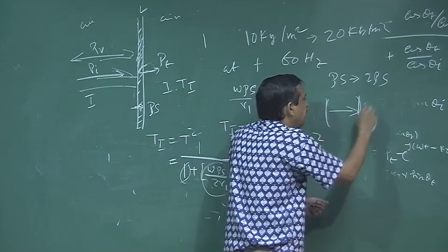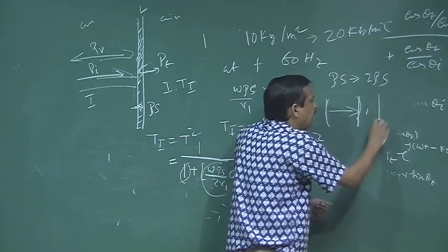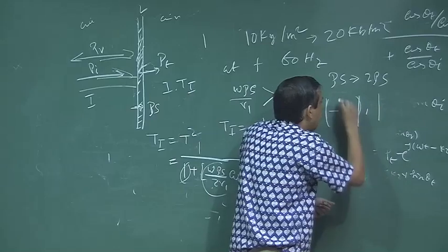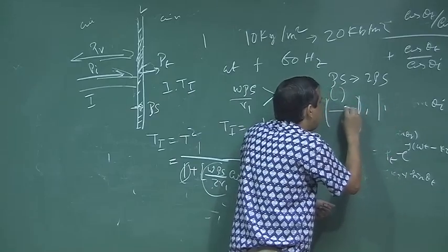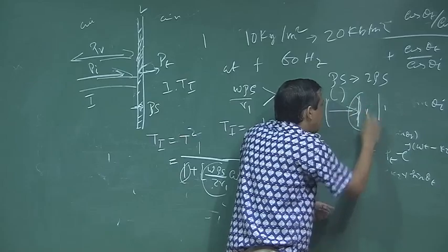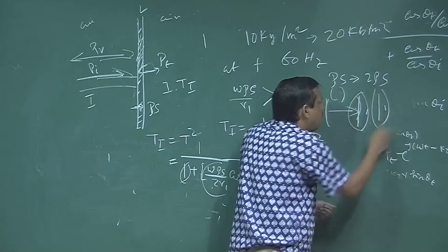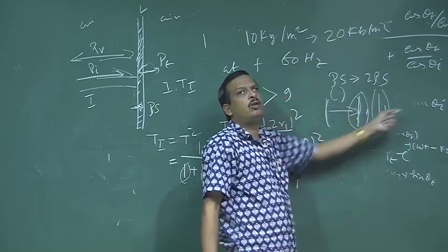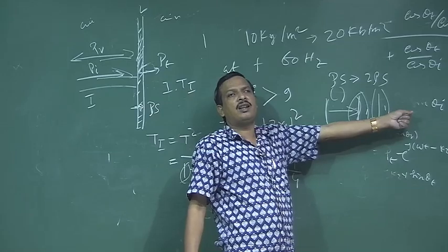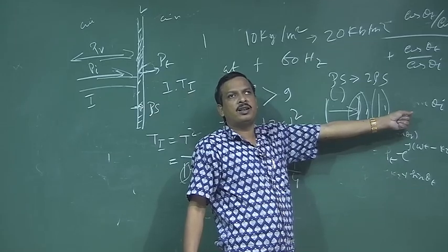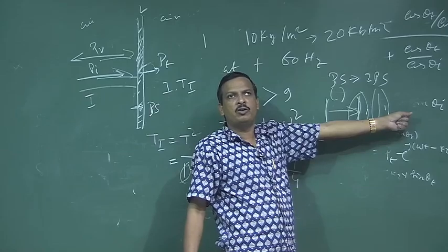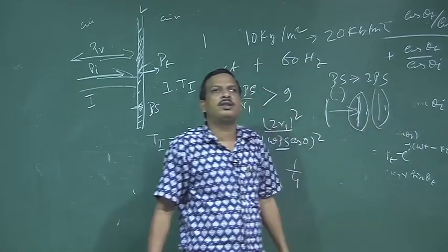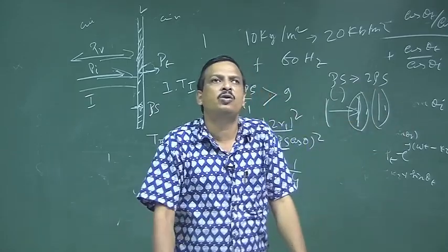If it is glass, then there is air, and again I have a glass, then the outside noise cannot go inside, because there will be a mass law effect in each of the two walls. So, inside the auditorium, if two separated glass doors are used, very little outside noise will enter. That is why this is mostly used in architectural acoustics.